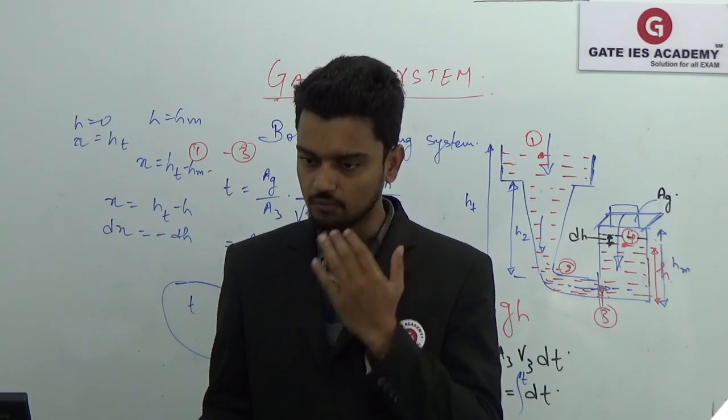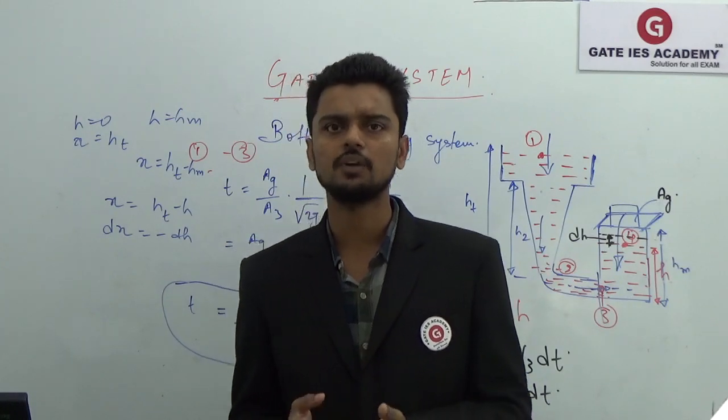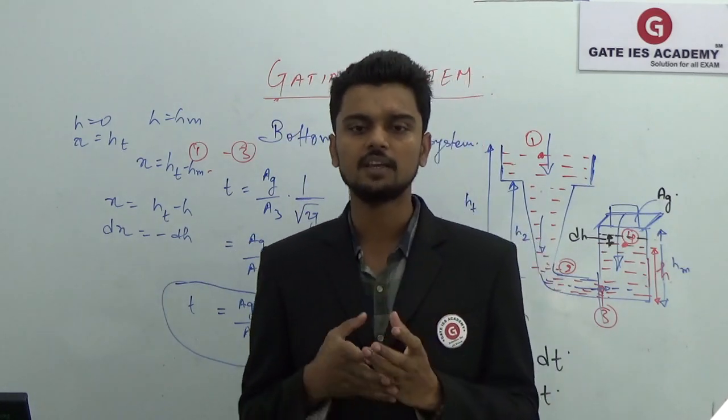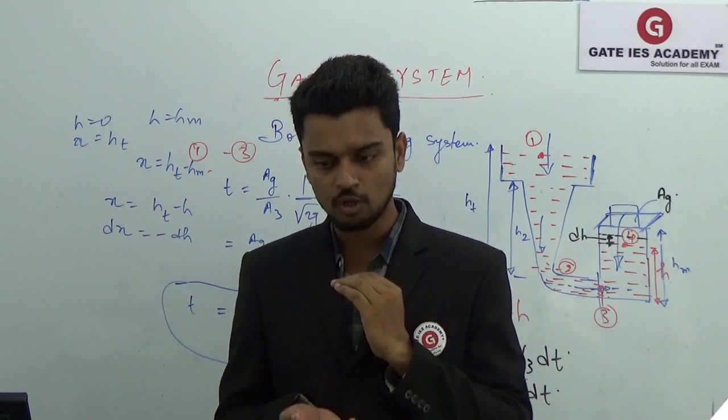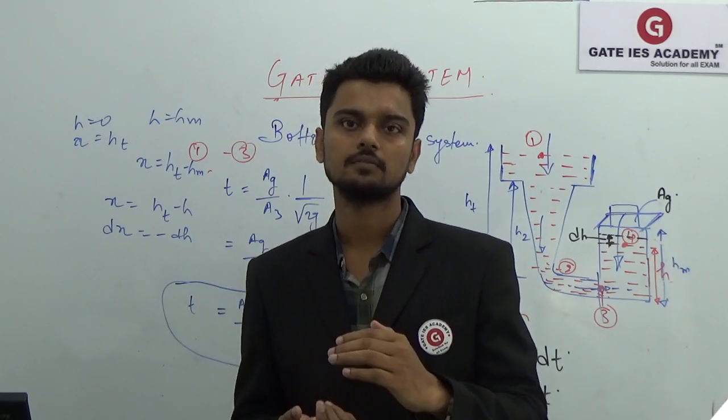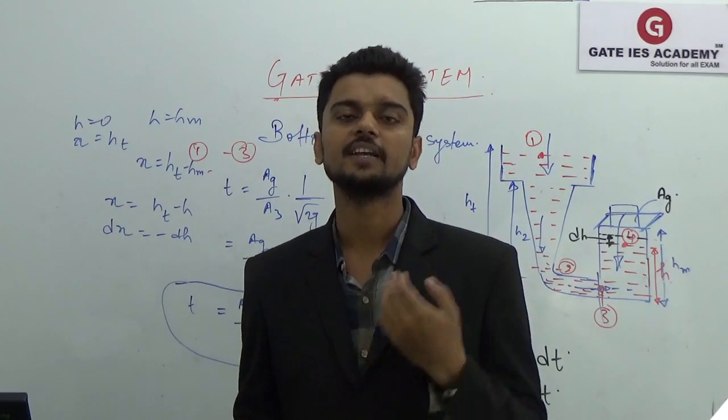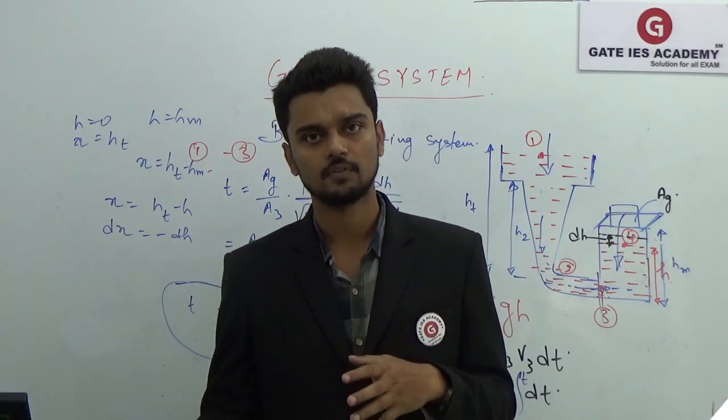So wherever we have large and heavy castings, we'll use the side gating system, and it is very easy to make the gating system on the parting plane, with the runner and the in-gate at the parting plane. It's easy.